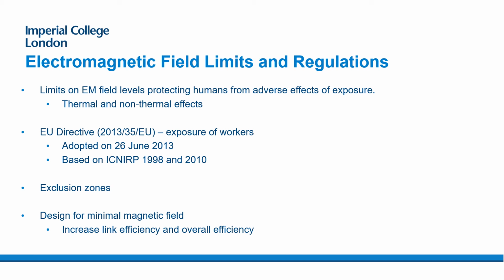field. Within the EU and various different directives around the world, there are laws that are based largely on ICNIRP, the International Commission on Non-Ionizing Radiation Protection, about the maximum magnetic field strengths that you can be exposed to. This might mean you need exclusion zones around a system.